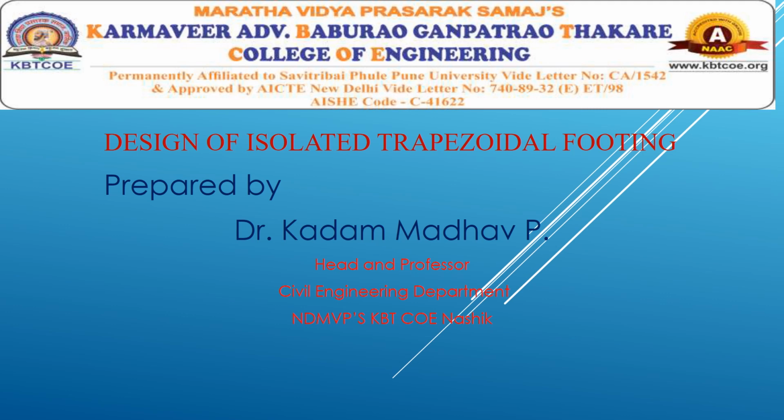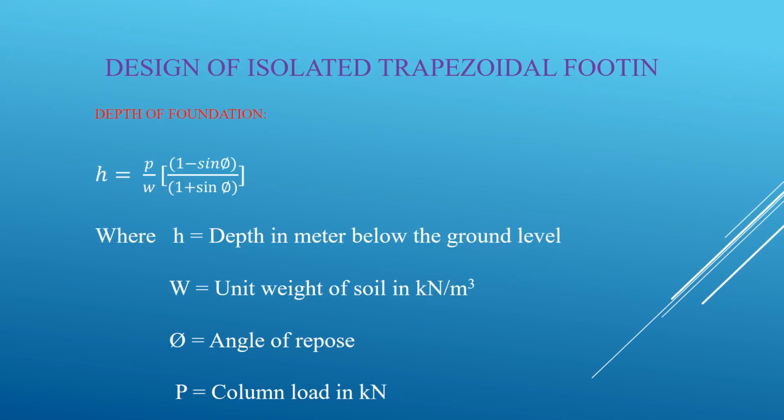Today we are going to discuss the design of isolated trapezoidal footing. For this, while you are designing the footing, the depth of foundation plays a very important role. The depth of foundation is measured from the ground level to the bottom surface of lean concrete.